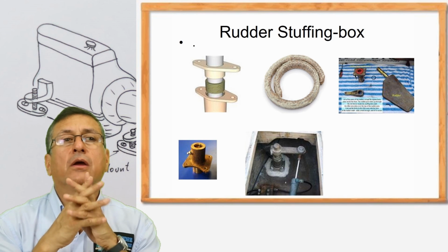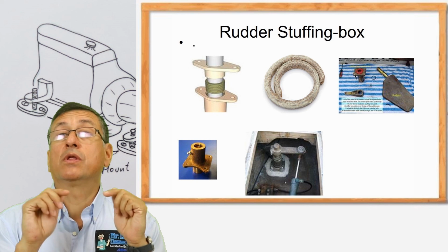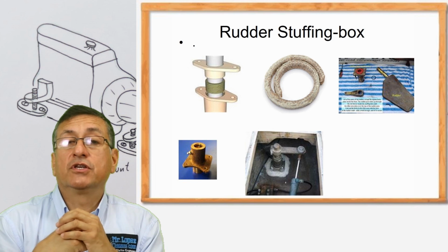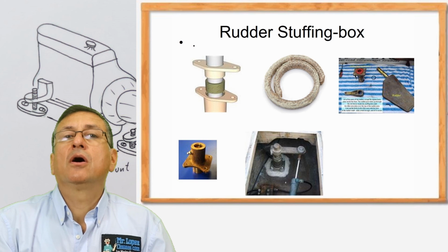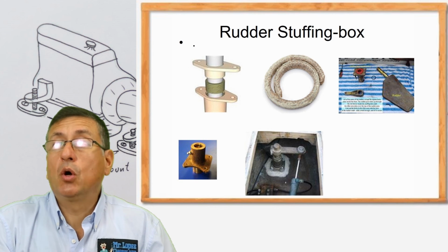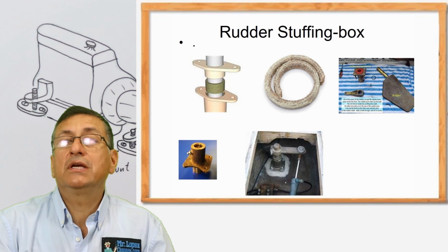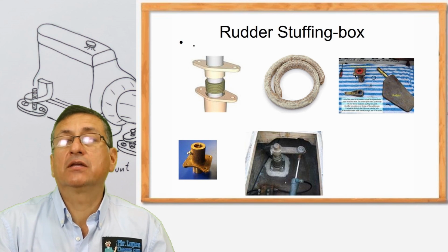Yes, this is another element where it's possible that the water penetrates and enters the boat, in the hull. Remember, there are different areas where normally the water penetrates the hull. One is the stuffing box of the shafts, another one the stuffing box of the rudders, or the through hulls. The through hulls, the different types of through hulls. If the through hull is improperly installed, probably water penetrates and enters the boat.